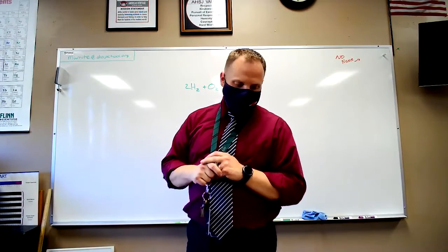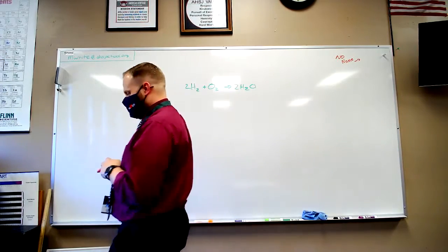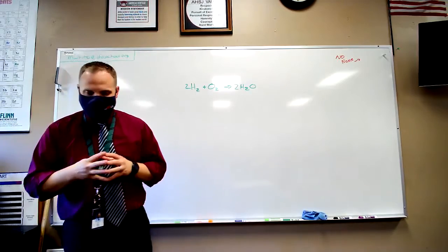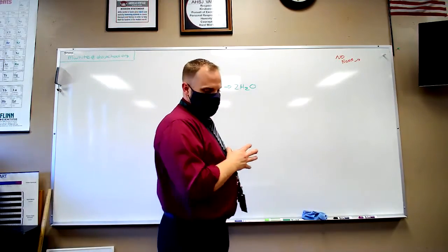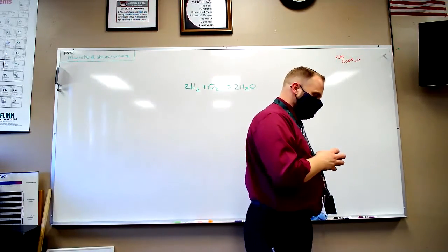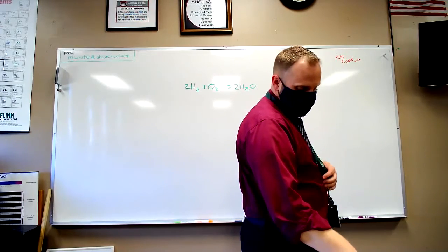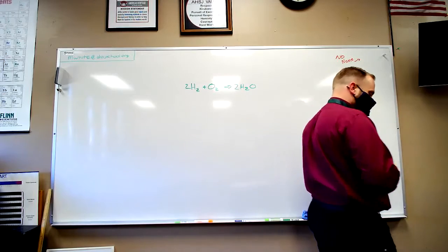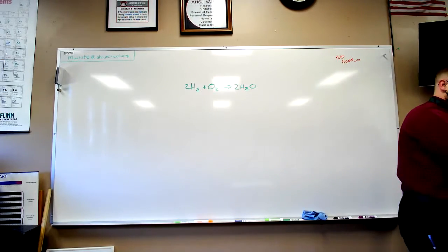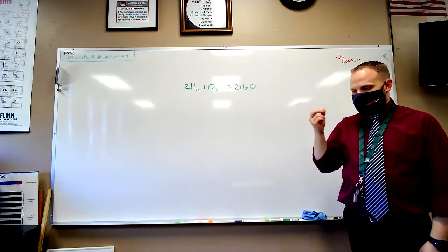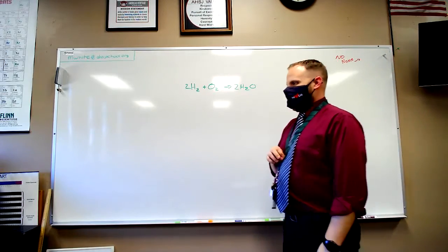So we use this technique in some other places. The book gives the example of underground pipes. We can attach a magnesium bar to it. It becomes what is oxidized instead of the pipe.